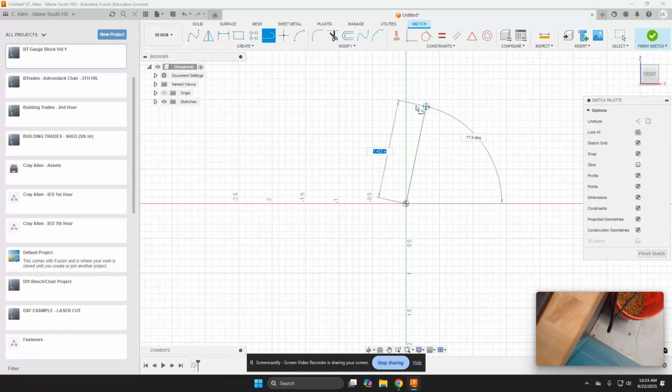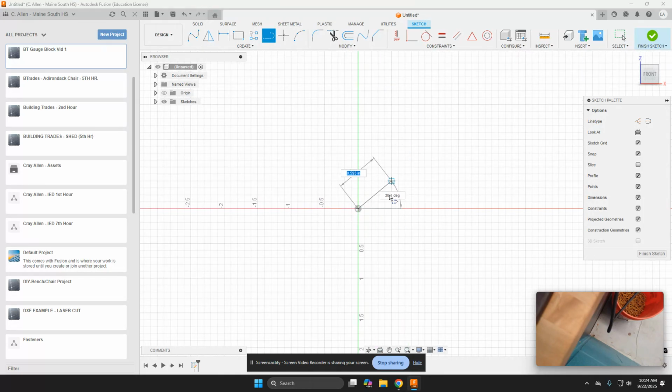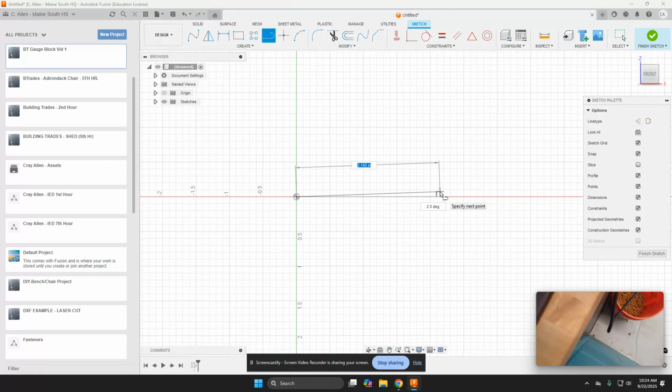So we're kind of drawing in space right now. So pretend like you're in outer space, and we're just drawing in space, right? Okay, so the easiest thing to do, and we want to do the least amount of geometric lines as possible, so we're going to just shape it. So I have a saying: shape it, constrain it, and then model it, okay? So we're just going to draw a little 2x4, and we don't even care what the sizes are, all right? So now I've got all these. As you see, we've got one black line and 3 different blue lines.